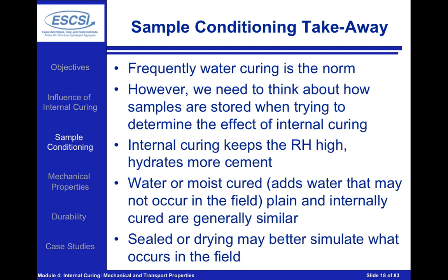Water curing and even moist curing in a high fog room or 100% relative humidity room is going to add water to our concrete to fill in some of those pores. This is going to add water to the plain concrete, and it's going to add water to the internally cured concrete. And in both of these cases, what we're going to typically see is that the plain and internally cured concrete are going to behave in a fairly similar manner.